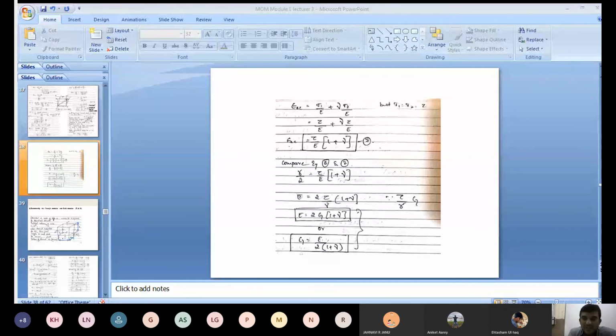Now this is the relation between Young's modulus and shear modulus. Now how do we derive that equation? First you consider a square lamina of equal sides, then a shear force is acting on that lamina. Now we will express the strain induced: the normal strain induced along the diagonal AC is equal to half of the shear strain induced in the lamina. That is the first step. Second step, we will apply the generalized Hooke's law. As you know, the generalized Hooke's law gives the strain along that direction.